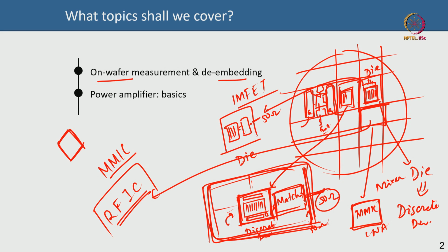Now in that case, measurement using on-wafer techniques is not suitable, because this is not on-wafer now, it is a die level device or an IC or whatever. So when you are talking about die level, the measurements will be different, because you do not have these giant CPW pads here to enable GSG probes to probe them.